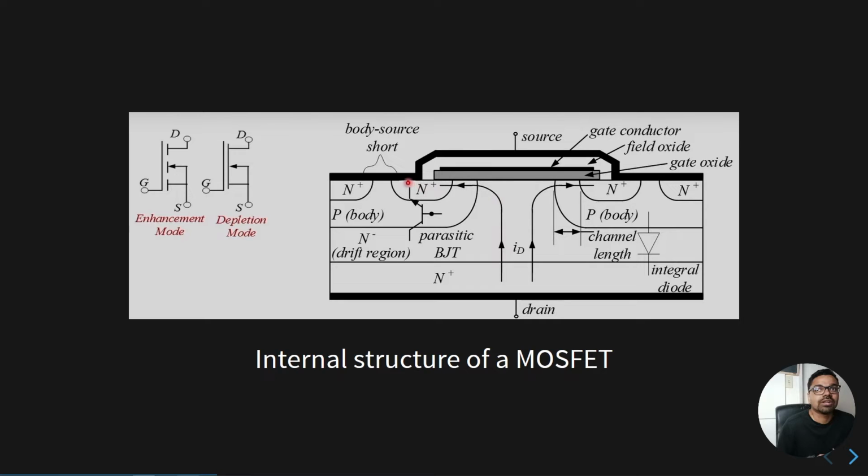This is very important, especially in a few power electronic circuits where you want the circuit to conduct in both directions. You don't need an additional device connected in your circuit. The MOSFET can basically allow you to conduct bidirectionally. But we will focus a little bit more on this diode later on.